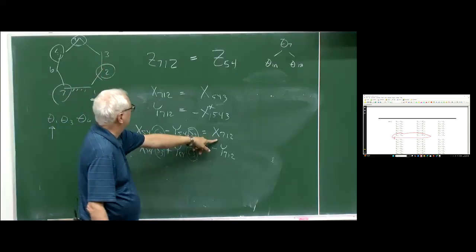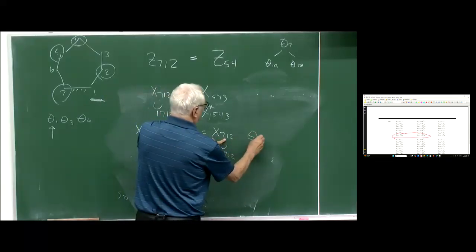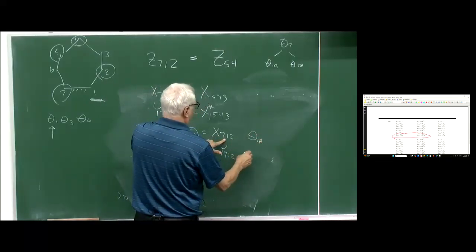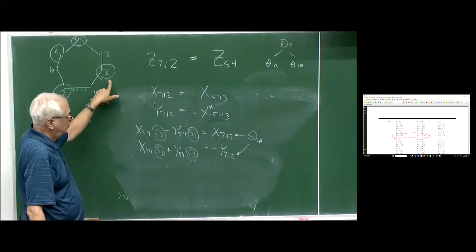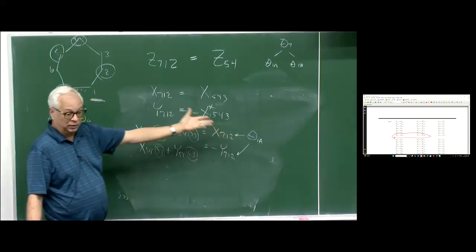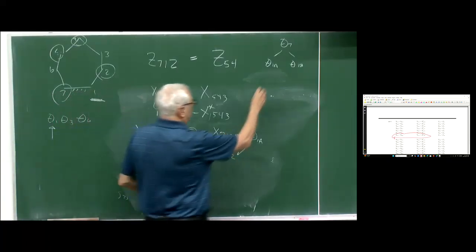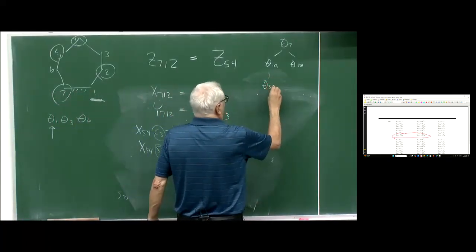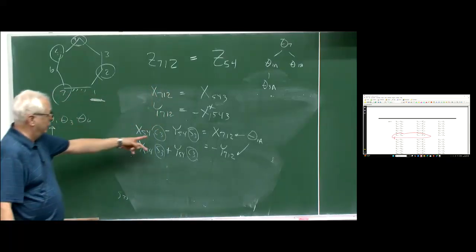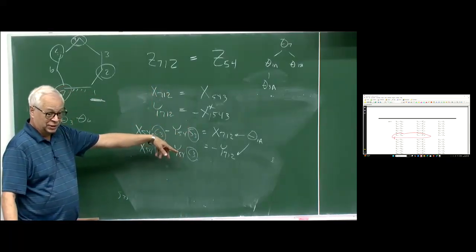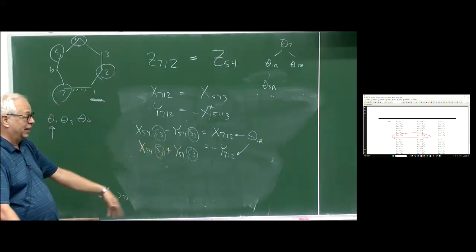Over here, I'm going to take theta 7. Oh, I'm going to have to take theta 1A. And then theta 2 is given. So for the A case, the right-hand side will evaluate to numbers. Solve two equations, two unknowns. I know the sine and cosine. If I was writing a program or doing this in a problem, I would probably stop right now and take my two solutions, S3 and C3, square them and add them together and see if they went to 1, because if they didn't, I've got a mistake somewhere.